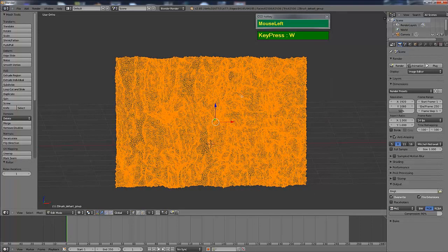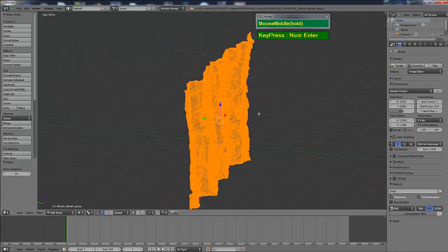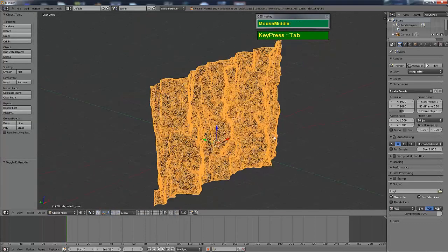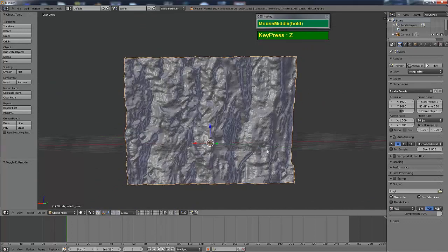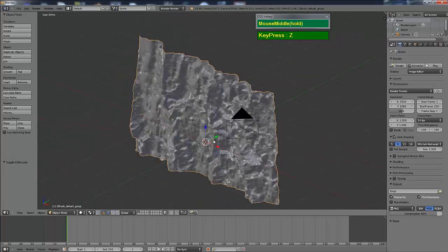Depending on the speed of your computer and how heavy this mesh is, this is going to take a while. So I'm going to apply a value of 20 iterations to spread out the triangular meshes. Now Blender is processing the mesh and relaxing it. Now it has relaxed the mesh, and if I press Tab to go to object mode just to check, and then press Z to turn on shader mode, you can see that I did not lose that much detail on the mesh.